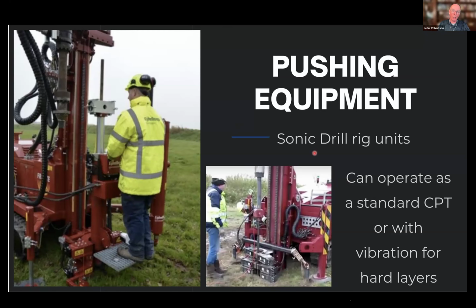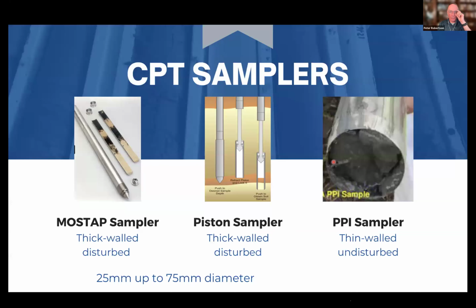So this is now becoming quite popular in regions where you've got complex ground conditions and where sonic drilling is very popular. And the reason sonic drilling has become popular is it gives you a continuous core that you can look at. Now, when it comes to looking at the soil, I said that people have added cameras, which is a bit cumbersome for CPT, but the Dutch, for a number of years, have developed simple little push-in samplers that allow you to get a soil sample using CPT pushing equipment.